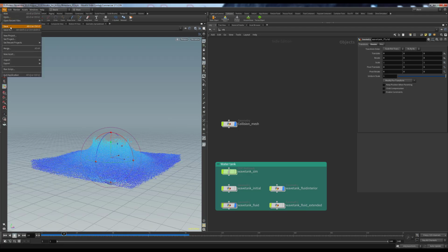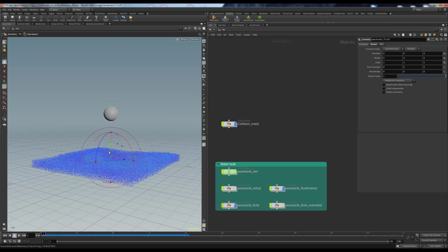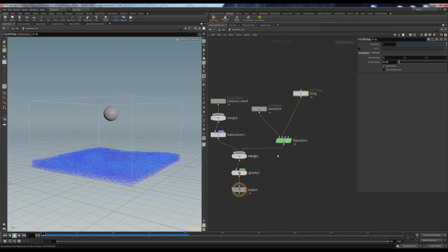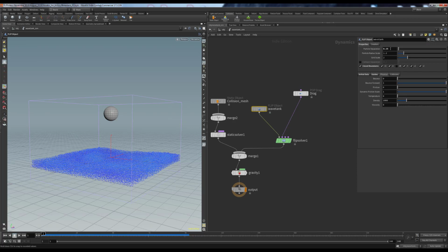Let's see, because we are going to use this one in many lessons. So now you know if you like to have a more complex simulation, we have to go here, select a wave tank container, and say, for example, that we like to have 10 centimeters for the scaling. And again, if we go to simulate, it will work better than the previous one. Obviously it will not be the best one, but it's better than before.